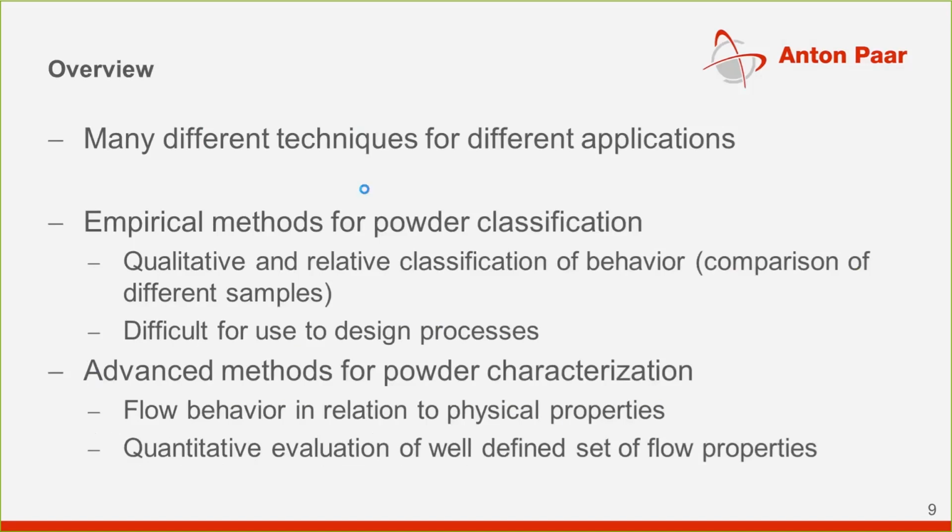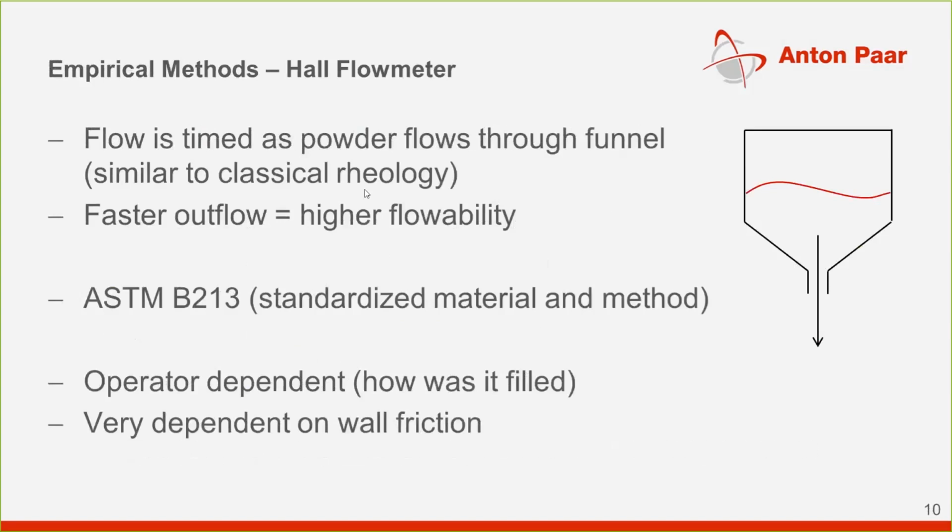One quite common method that is used quite a lot is, for example, the Hall flowmeter, which is very similar to classical rheology. What happens here is that a powder is in a funnel. The funnel is opened, and the time is measured for the powder to flow out of the funnel. This is actually a standardized method.